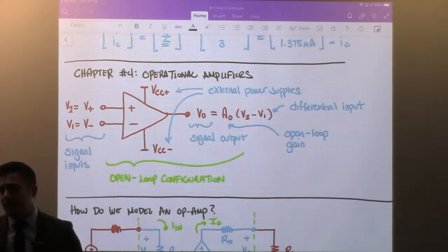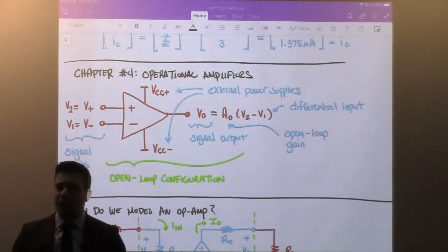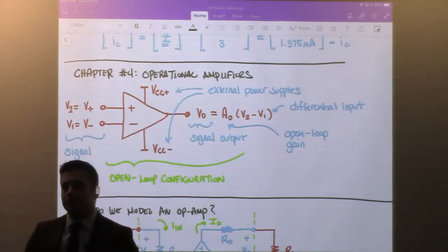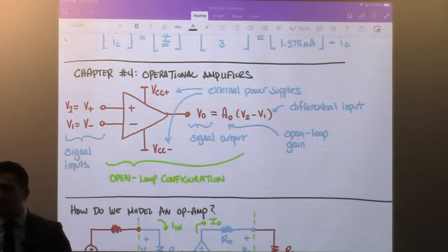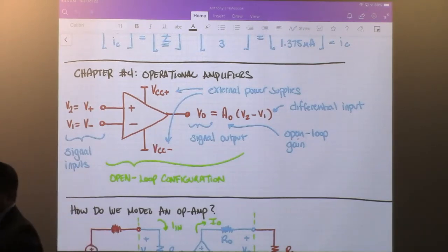Amplifier, that doesn't apply, right? You could have a signal with a power of 10 milliwatts coming in, and you could have a signal going out with 100 watts power. And then obviously the amplifier works for DC, AC, essentially anything that stays within the linear range. Going back to the previous question that I asked, normally it's positive or negative 12 volts, positive or negative 15 volts. Sometimes for digital circuits you'll see plus or minus 5 volts or 0 and 5. Those are common values for the supplies.